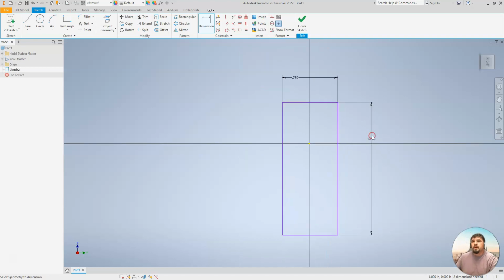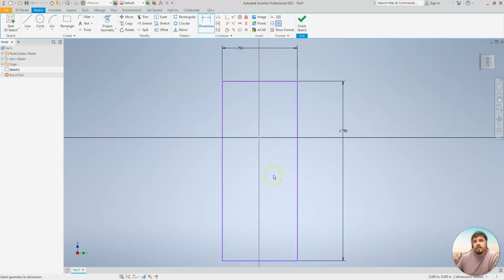Boom. Okay, now the next thing we need to understand. Notice I just put this shape out in the middle of nowhere. That's perfectly fine. But a common thing that I want everyone to understand is that these models should always be on the origin, or if it's a complex model, understand where you want your origin to be. Because origins can be easily dropped down in this box here by being able to view it.